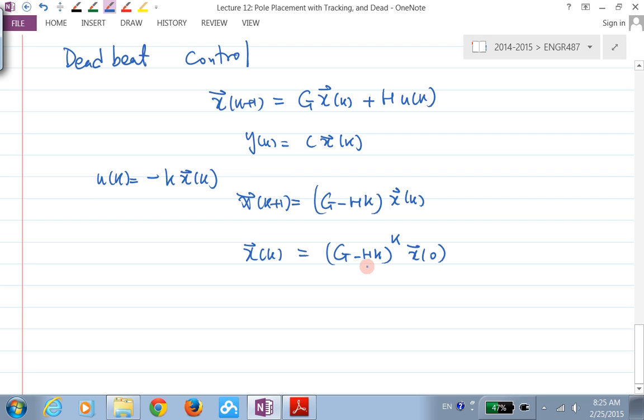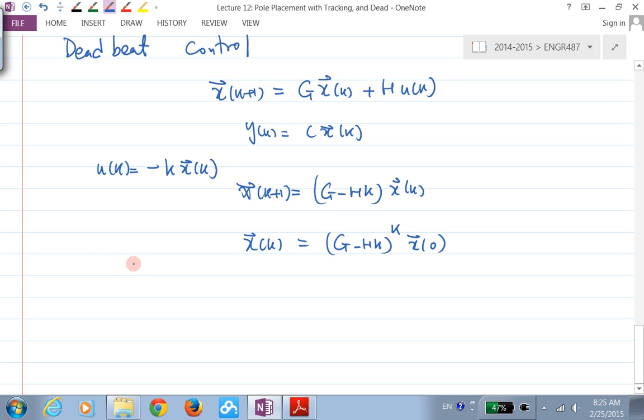Do you remember in the previous lecture we were examining things? You have a response, let's say z over z minus a. That's the pole here. What does this correspond to again? It corresponds to a to the power of k. If I put this a as 0.5, it's 0.5 to the k. If I put this a as 0.3, it's this. If I keep reducing it, guess which one reduces to 0 in the fastest fashion?